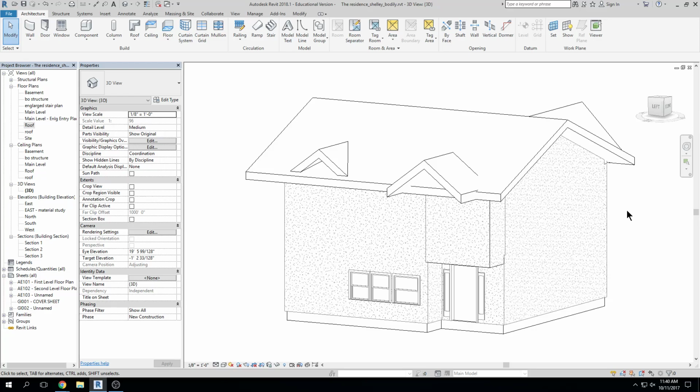And you think, well, I'll never cut a section through there, or there will never be an elevation of that area, so it doesn't matter. That always backfires. Somebody else gets into your model down the road, and then they end up having to do the cleanup and let you know about it. So I know it's easy to say, but it's probably better just to use the join roof tool in the beginning and clean it up nicely.